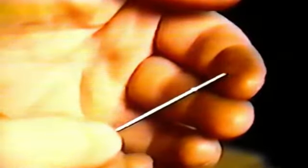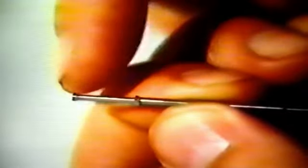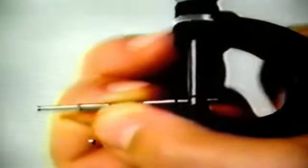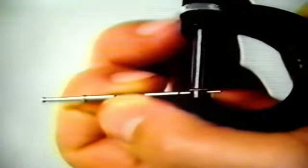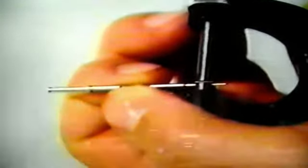You'll also find a number and letter on the metering rods, but you'll probably need a magnifying glass to see them. The letter tells you the type, and the number, usually 2 digits, indicates the size. Using a micrometer, measure the size at the second step of the rod. The number and your reading should match. However, we have found cases where 2 different sized rods were used in the same carb. Needless to say, this causes drivability problems.